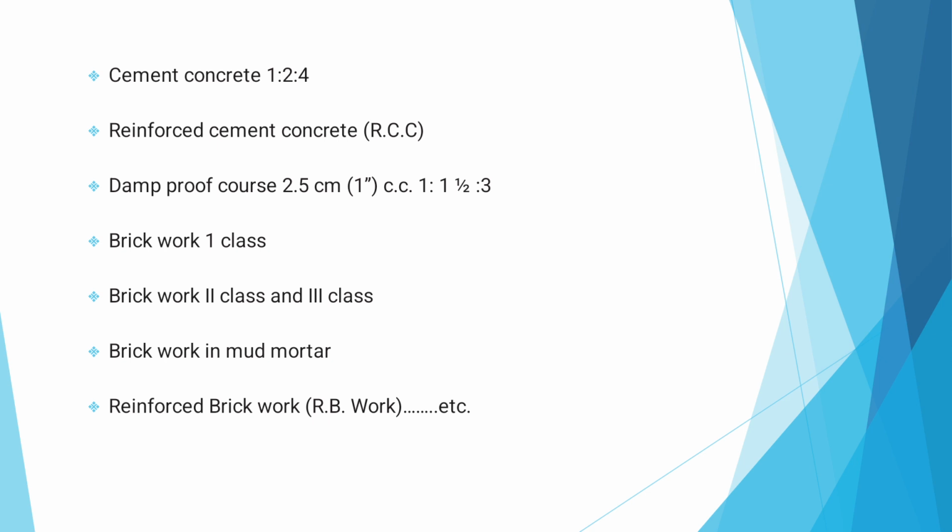When the sand is fully saturated by submerging, its volume is same as dry volume. The difference in the original volume and final volume is the bulking and the percentage of bulking is therefore capital V minus small v divided by small v into 100.